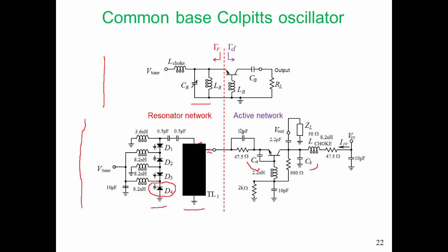Many of these other elements provide RF short circuits or RF open circuits. Of course, we have to bias our transistor here, and so we have to provide provisions to enable us to bias our circuit but still let our RF signal get through.